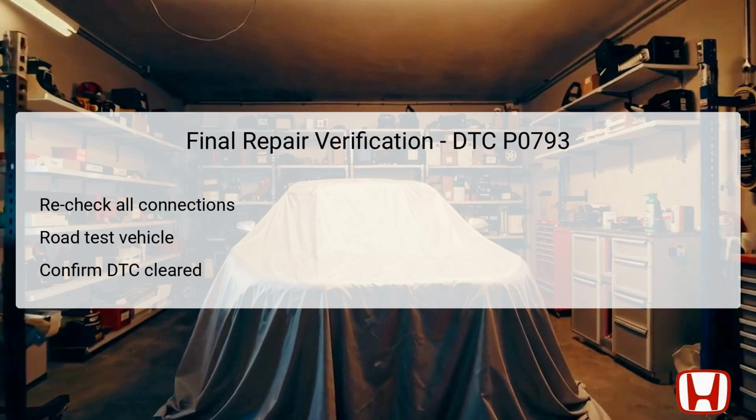Next, proceed with a road test of the vehicle under normal operating conditions to ensure that all systems are functioning smoothly. Pay particular attention to the transmission performance while driving, ensuring that there are no irregular shifts or warning lights. After the road test, use the HDS to confirm that no DTCs remain active in the system, especially P0793. This last verification step is essential to ensure that repairs have been effective and the vehicle is safe for regular use.